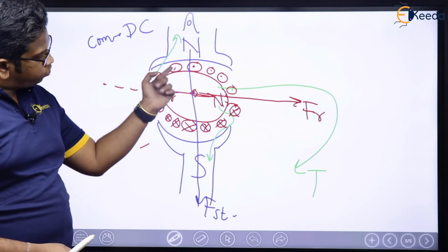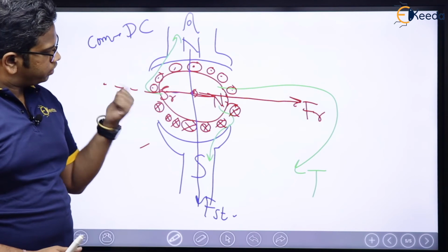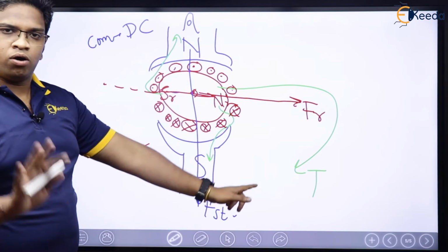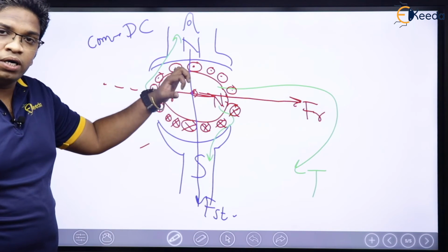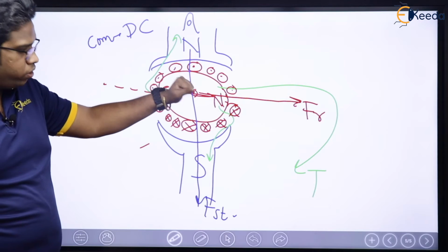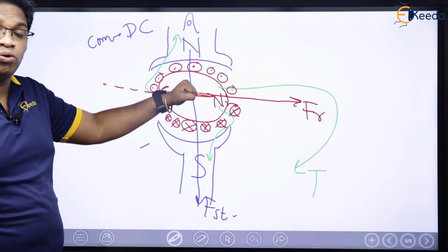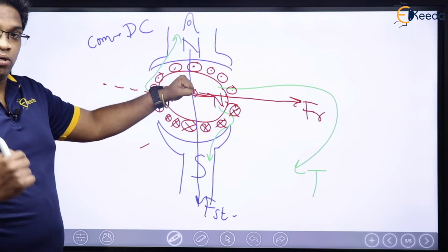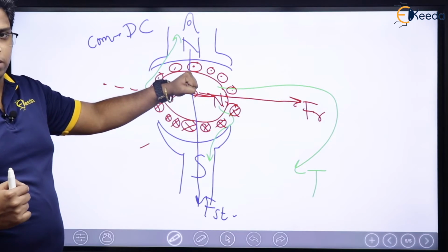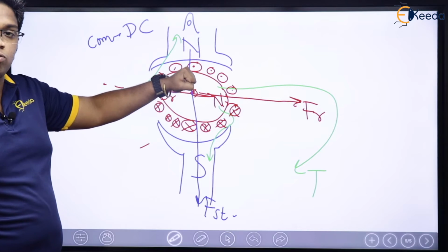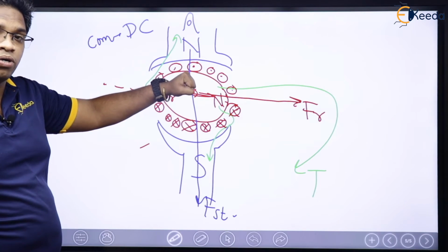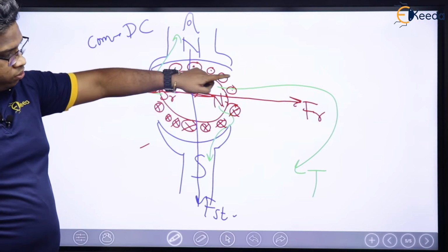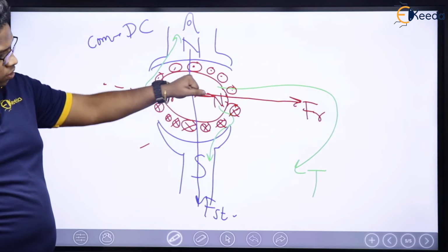Cross are the entering currents, dot are the outcoming currents, right? So torque will be there in this direction, already discussed. Now I am holding the rotor of this machine, trying to hold this motor. The moment I try to hold this rotor, what is going to happen? There will be a twisting moment in this direction, because torque is in this direction, right?